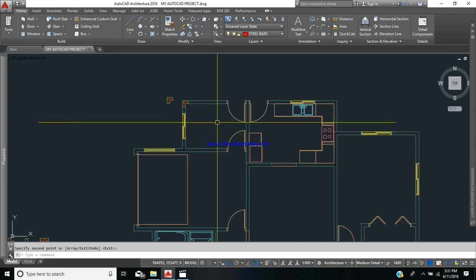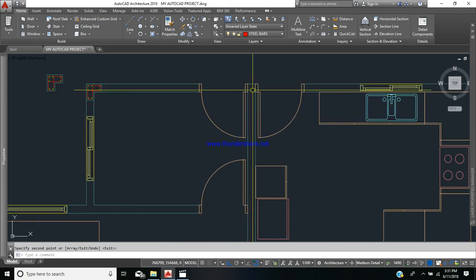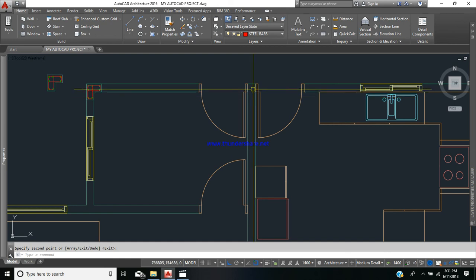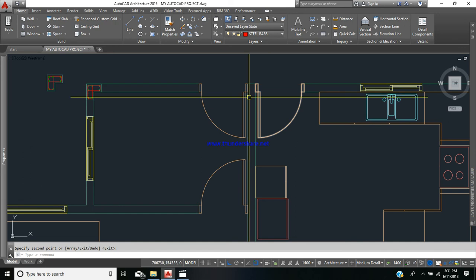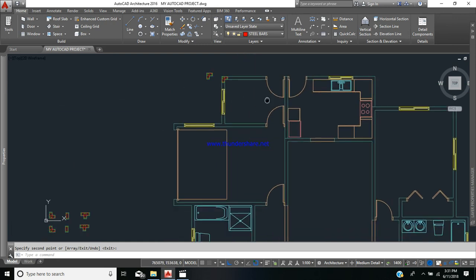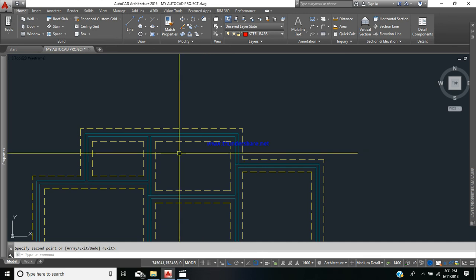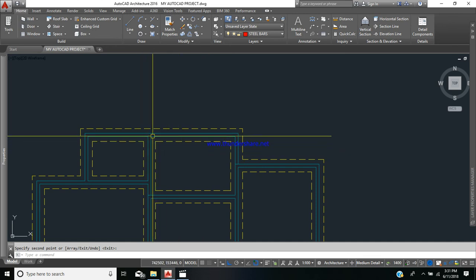In a similar fashion, we could also have placed a stiffener here. But based on that particular location, it couldn't accept the L or the T. Based on the shape of this wall termination here, we could only afford a straight stiffener. And so what some persons would have done is to start by putting in their stiffeners in their foundation.